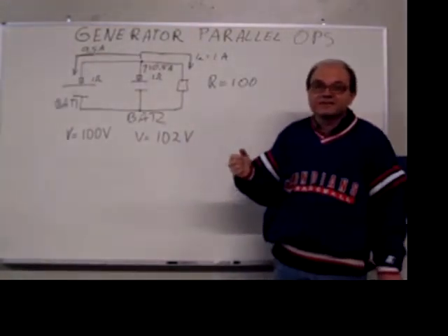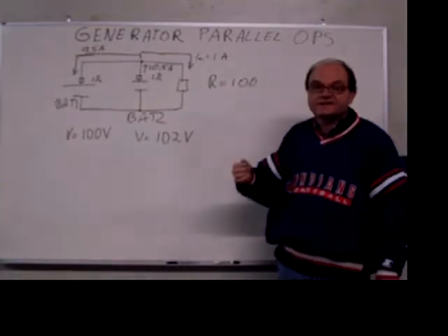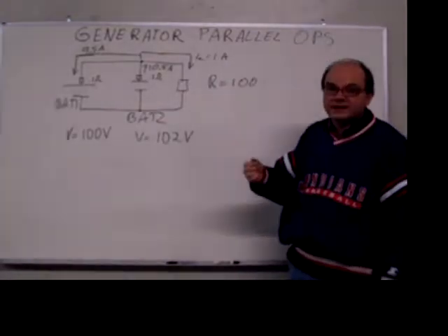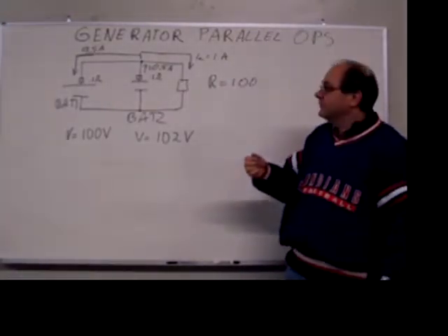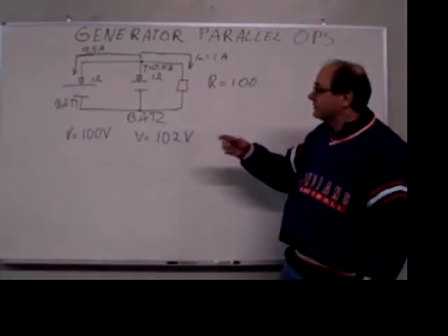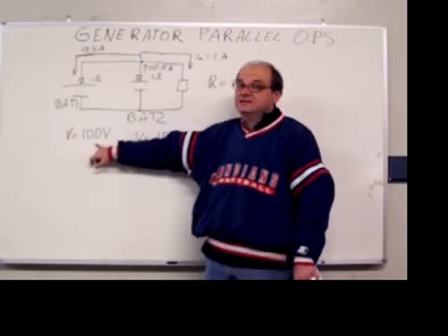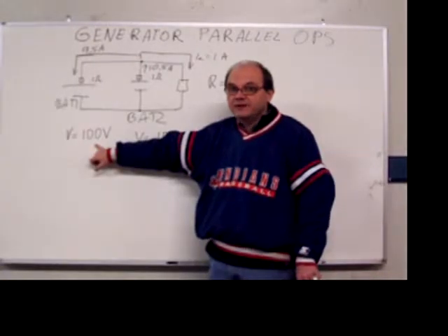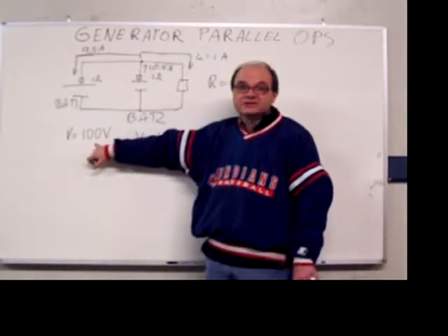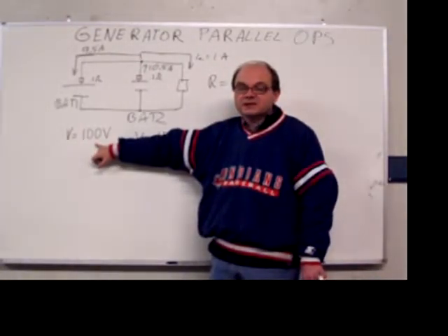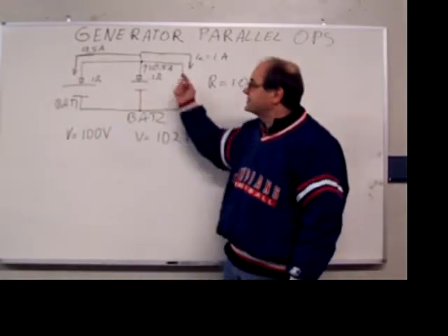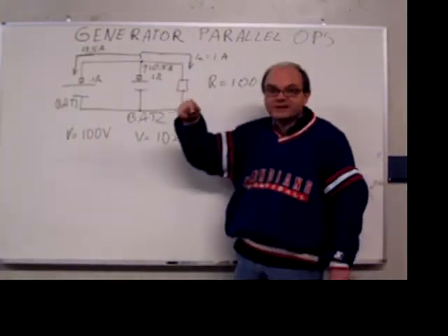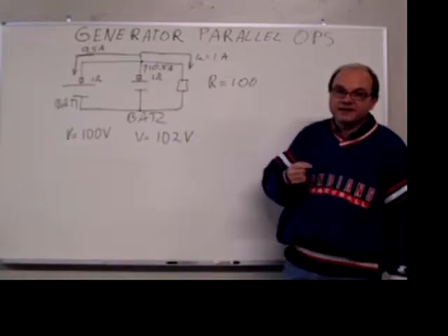You can draw several tens of amps, 20s or 30s or 50s, depends on what configuration you have. That will overheat your generator on the lower side, because your generator is not really a battery, but it is actually a generator with a coil. So you're actually feeding a rather large current at that voltage which you have selected into the other generator set.